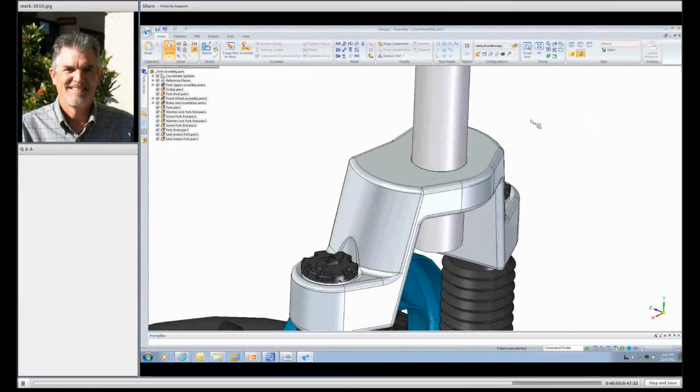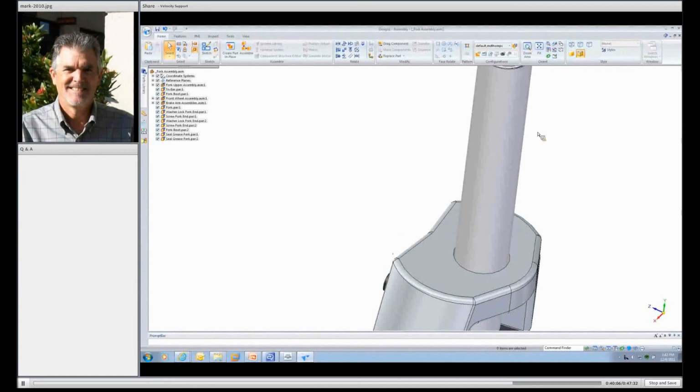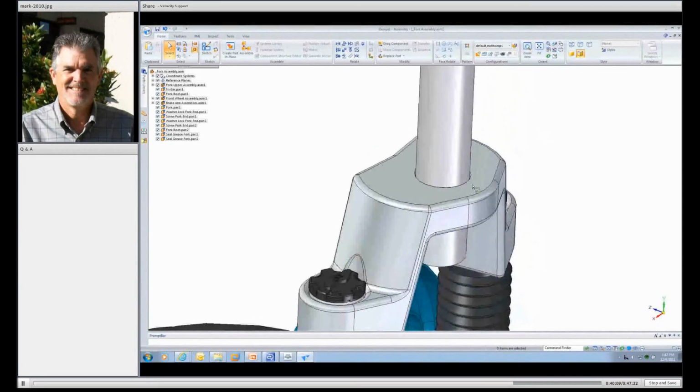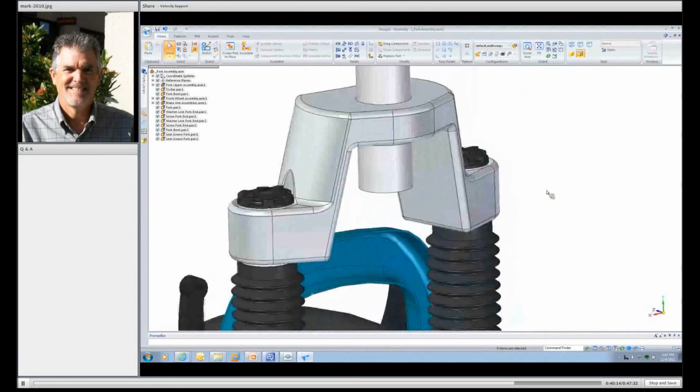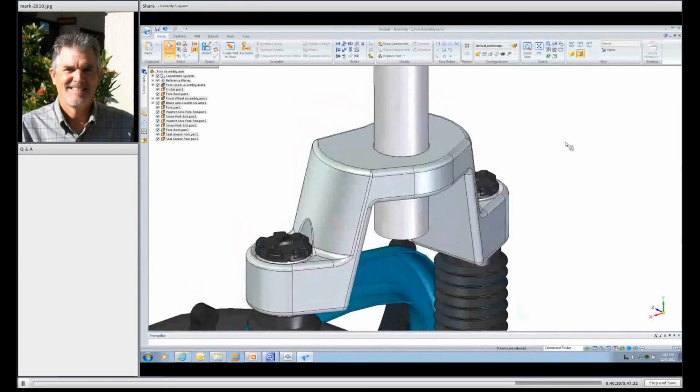And then I'm going to pick my primary axis, and I'm going to move the model down, and in this case we'll just move it down to the bottom of our ring here, move it into the position that I want it in, and you can see how easy it is to manipulate my model at the assembly level because of the synchronous model. Again, using the steering wheel and live rules even at the assembly level.